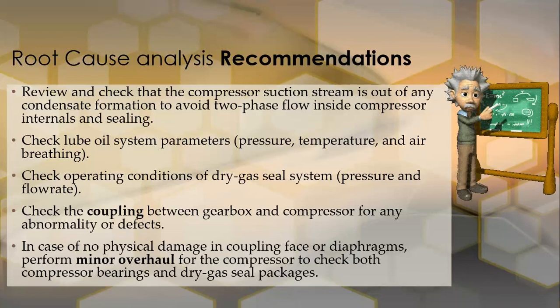any contamination of liquid. And when we sent this data to the vendor, they were also shocked, because there is nothing normal to let the propane generate liquid inside the compressor, as the propane enters the compressor, as mentioned before, at minus 35 degrees Celsius and exits the compressor at about 93 degrees Celsius. So with this increase in temperature, there is no way that there is liquid generation in the compressor itself of propane gas.